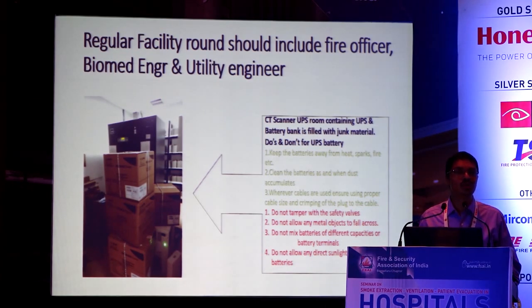It has been secluded, the walls are secure, and the fire precautions were taken when we built the walls. Everything has been done, but see the adherence. You can see the cardboards, it has been completely messed up. So it's very, very important that we as a team ensure that sustenance is done. Regular rounds are a must, and we must not compromise on this, because fire may happen only once in a while, but when it happens, it's a catastrophic condition.